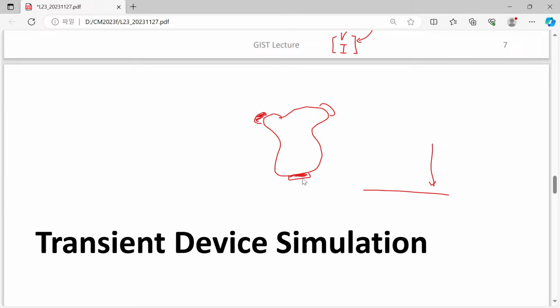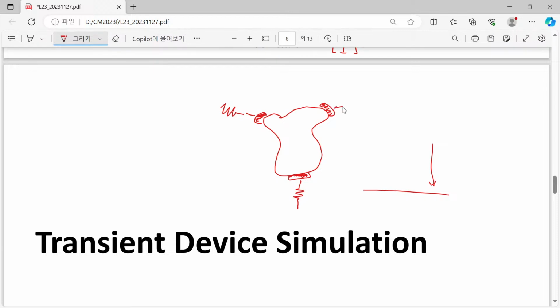If you do it correctly, then each terminal can have its terminal resistance. So we can apply a certain voltage, another voltage, and another voltage directly to these external contacts, and after that there will be a certain voltage drop across the internal contact terminals: R1 times I1, R2 times I2, R3 times I3.